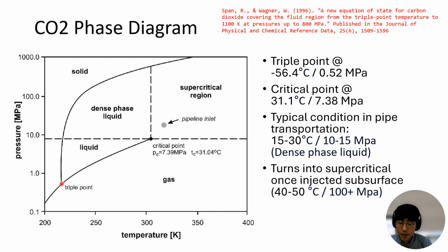And this phase diagram is split by three different lines. The first line goes like this, and the second line comes from the triple point to the end here, and then the last line is between the triple point and the critical point. These lines indicate the boundaries between two different phases: this line indicates the boundary between solid and liquid, this line the boundary for solid and gas, and this one is for liquid and gas.